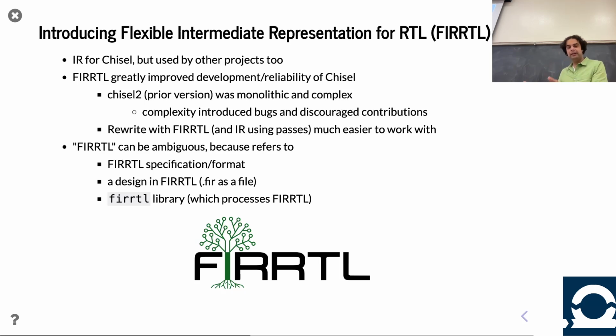So if you have a hardware design and you run it through the Chisel front end, you get the FIRRTL out, and you refer to it as the FIRRTL. FIRRTL also is a library, right? Which processes the FIRRTL. And this is the one that has deprecation warnings. So the Scala FIRRTL library is the one that's been end of life, but is still used in today's lecture. And the reason why is FIRRTL is now a dialect in a larger IR called CIRCT, which I'll come to at the very end.